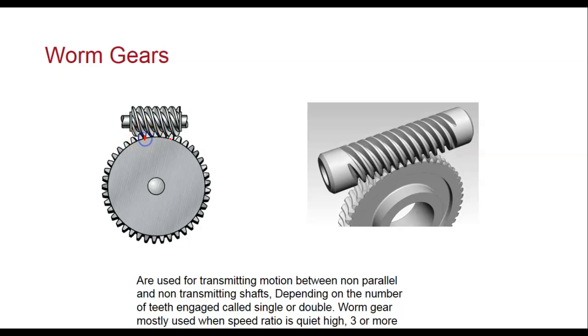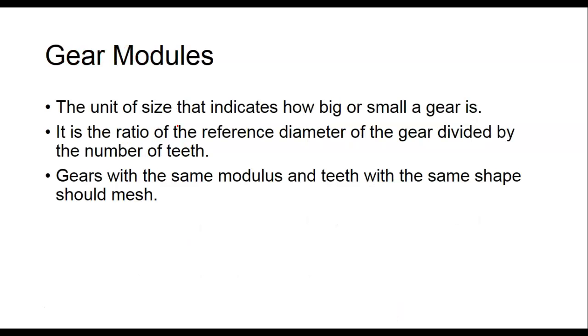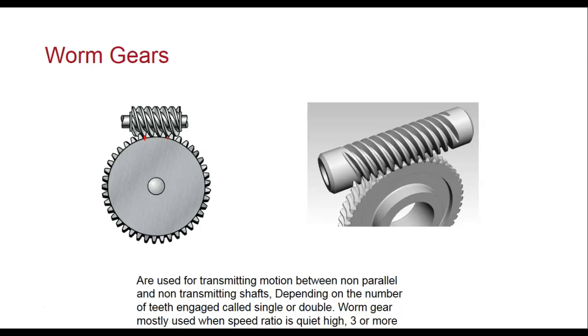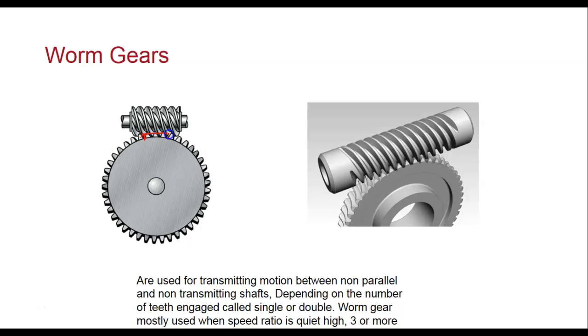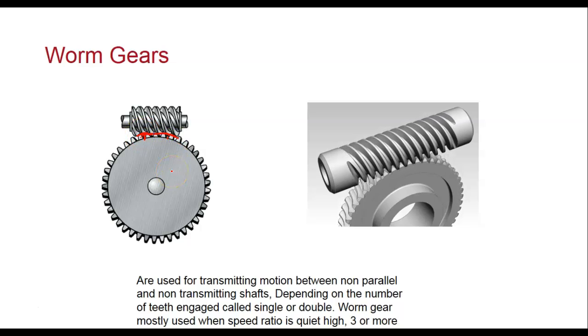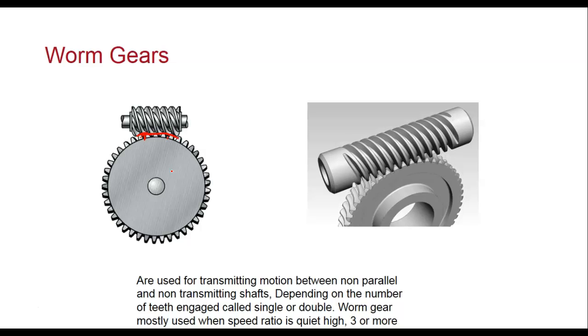Can you see we got that gap there and your gap there? So to get higher torque, what they'll actually do, I don't know if they're going to come up here and show this, but I've actually seen them where they're basically slotted in the center like this. And these can transfer more torque because you have more teeth engaging at the same time. Are we okay on worm gears? Okay? Questions? Guys at home?